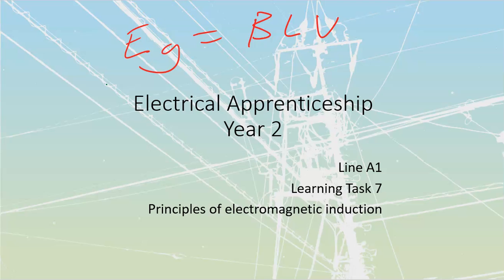What we will find is that as we change the current value going through a conductor, that current value is going to change the flux lines around that conductor, which are going to cut through that conductor itself, which is going to generate a back voltage pushing back around it. Once again, let's cover that once we actually get into our next learning task. For now, just note that we are going to have an induced voltage, but we're also going to have a counter EMF or a slowing effect that is also going to be created.